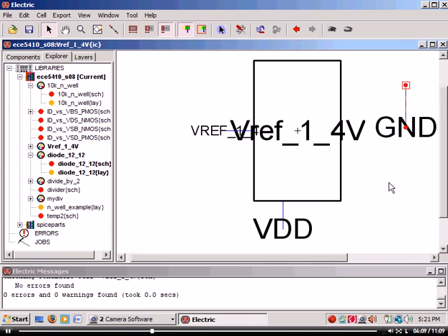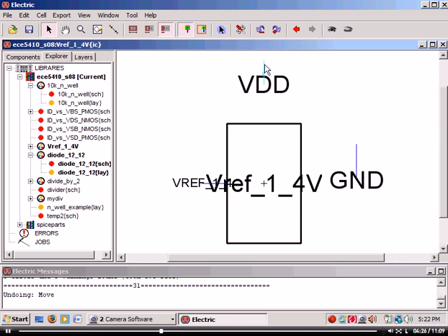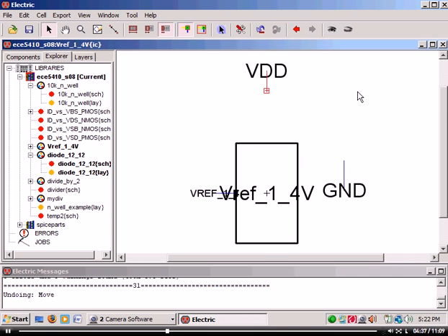Okay, so let's move this one, press X up here. Whoops, Control Z, and I got to make sure I get the pin. Once it's selected like this, I can do a Control J and rotate it. You can't select the port, you can only select the wire. Because remember, as I just said, it's a square. So if I try rotating a square, it doesn't make any sense. This thing.